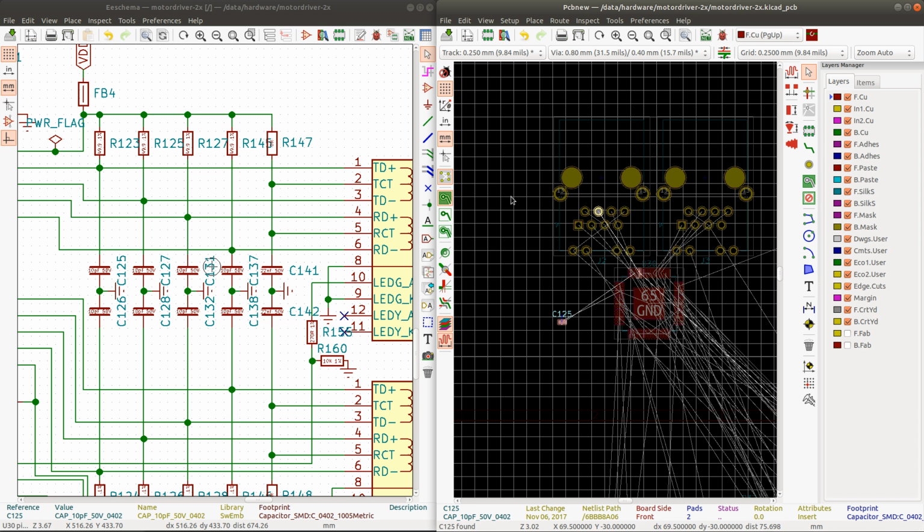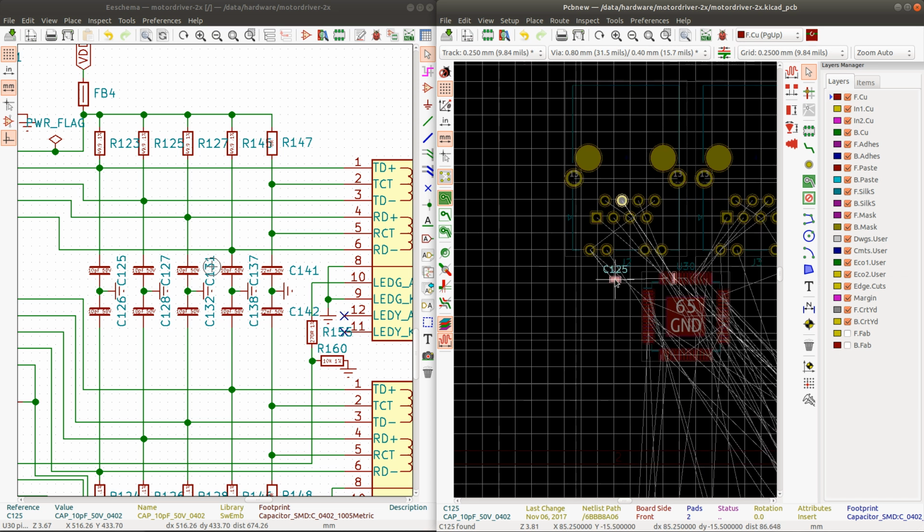The faster the slope of the signal, the more the trace will radiate. So it's usually beneficial to smooth out the slope of the signal, so that it doesn't just go straight up, but rather becomes a smoother slope. So that's why they place capacitors here from each of the lines to ground.